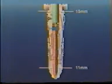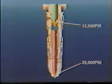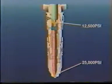This difference in diameter reduces the pressures in the timing chamber to approximately 50% of the injection pressures. Therefore, if the pressure in the timing chamber is 12,500 psi, pressure in the cup can be as high as 25,000 psi. This reduction ratio allows the injector train to operate with minimum stress and wear, yet still produce extremely high injection pressures.